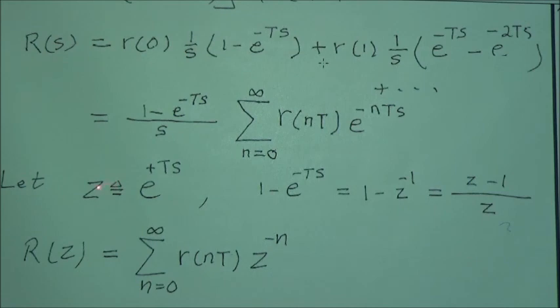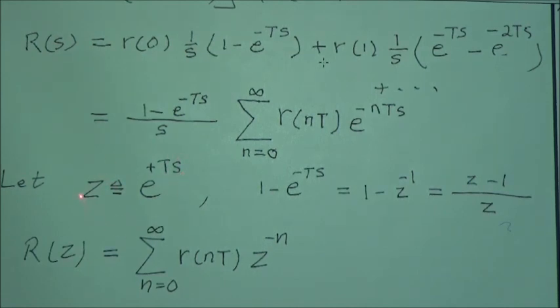And as you remember, we also call it a mapping from S-plane to Z-plane. Notice that when s equals 0 on the j omega axis, e to the 0 is 1, so the magnitude of z is equal to 1. That's what gives you the unit circle. And then when s moves into plus and minus values, then this goes in and out of the unit circle.